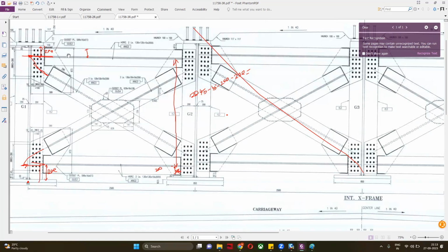And the same will be there if the bracing has internal moment because of self-weight. That moment will also not be transferred to your girder. Only shear force will be there, and another thing is your axial force. Axial force will come, compression and axial force will be taken.